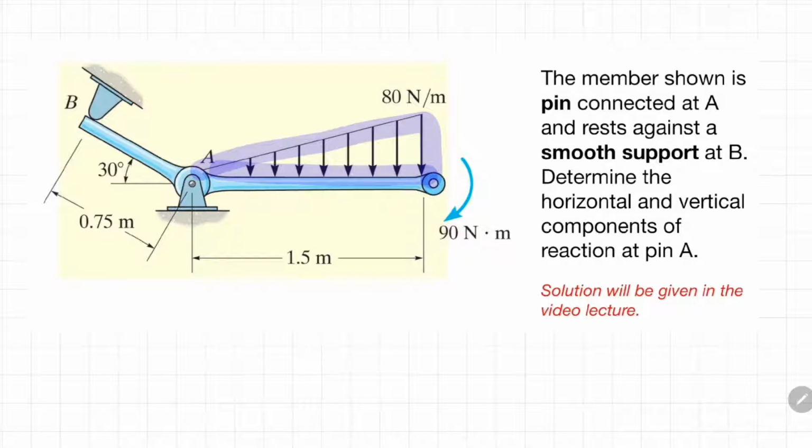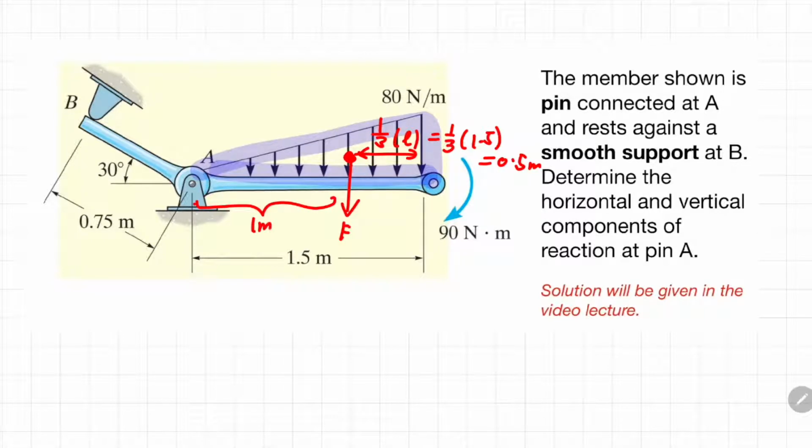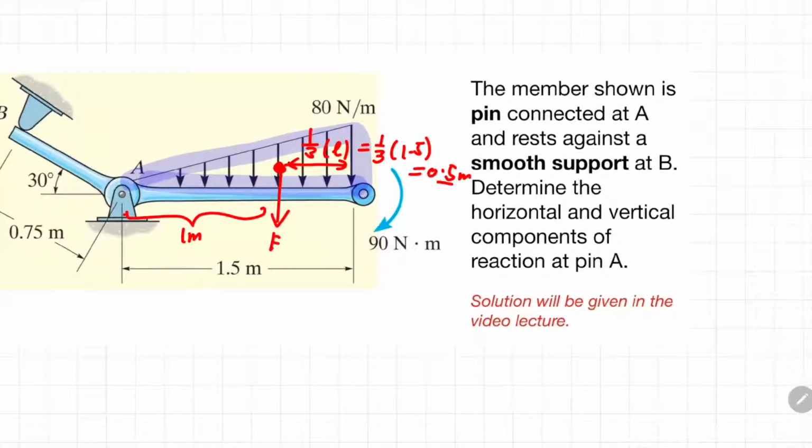Okay, in order for us to decide the direction of the forces, we have to convert this distributed load into a single concentrated load. So the concentrated load, based on the principle of the distributed load, would usually happen somewhere not in the middle, but if it's a triangle, it would happen like 1/3 daripada the bigger region, okay? 1/3 of the overall length of 1.5 meter. So kalau you calculate guna your calculator, 1/3 of this length is 0.5 meter. So it means the distance from A to the concentrated force converted from the distributed load would be 1 meter lah. 1.5 tolak 0.5 akan dapat 1 meter.